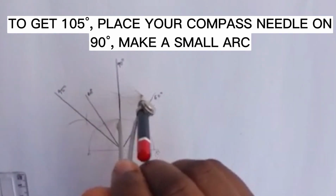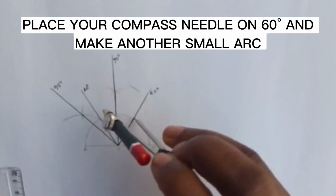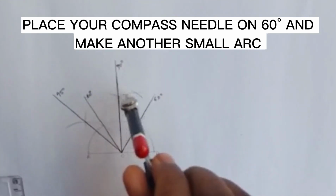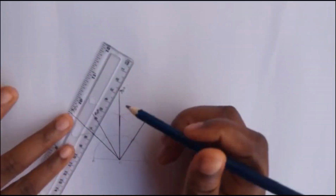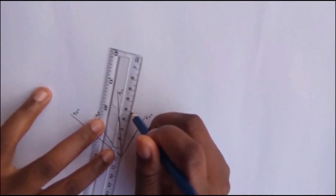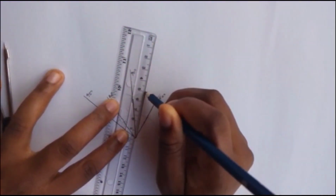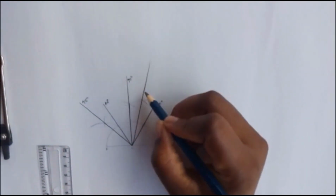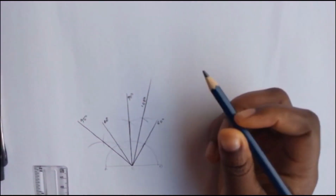Now to get 105 degrees, what you're going to do is you place your compass needle here on 90 and make an arc, and you place your compass needle on 60 and you make another arc, and then you join the line. And this right here is 105 degrees.